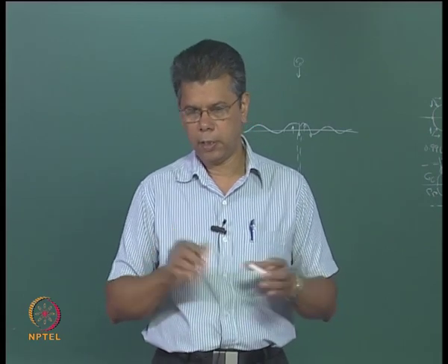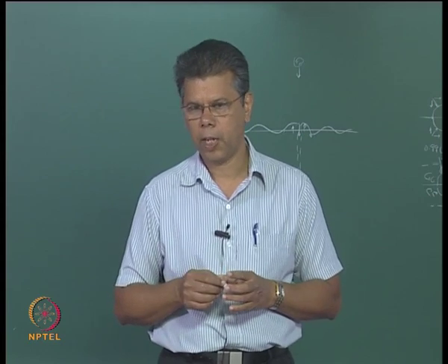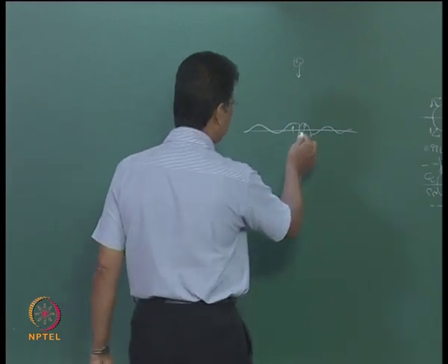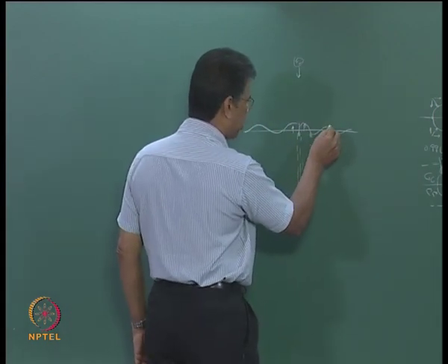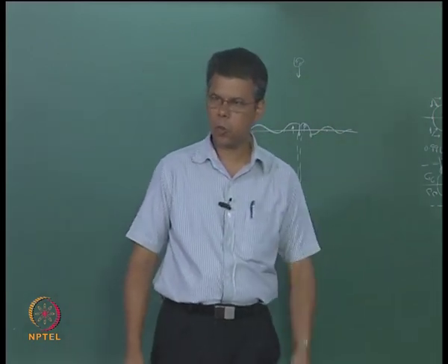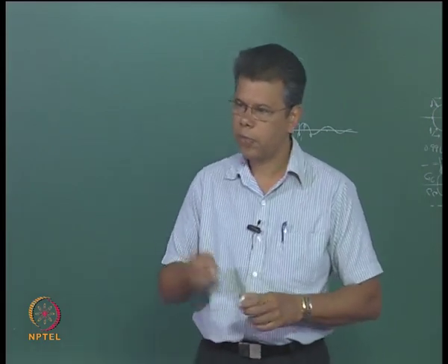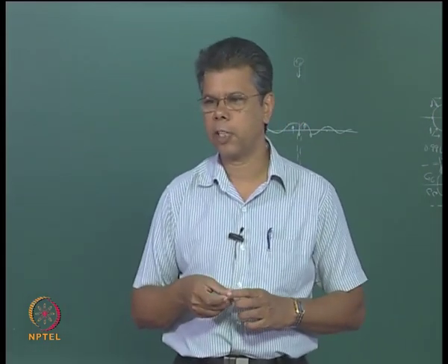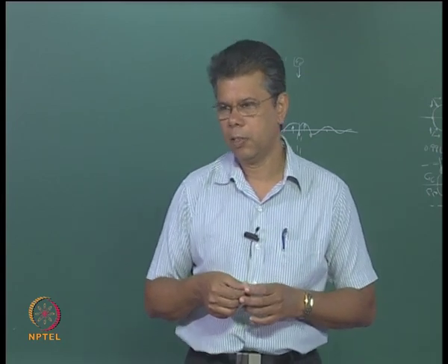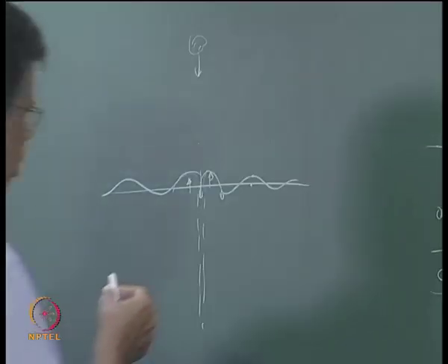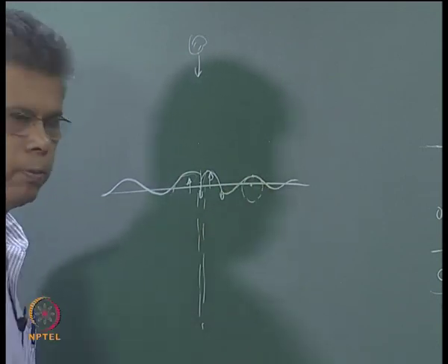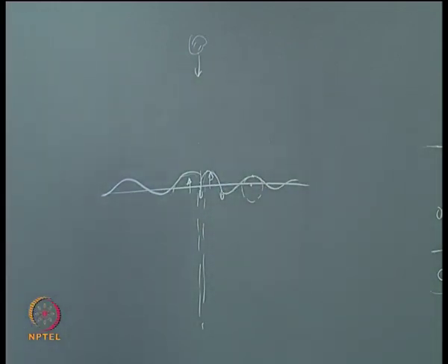So waves are generated when the ship is moving through water, compared to still water. Consider a water particle here, and now due to the action of the wave, the water particle has moved up. The water particle possesses mass, and when that mass is lifted, what type of energy is associated with it? It has potential energy, isn't it. So the wave now has potential energy, and you know that the water particle inside a wave has an orbital motion.